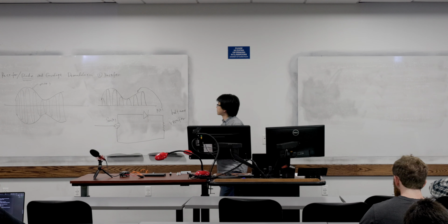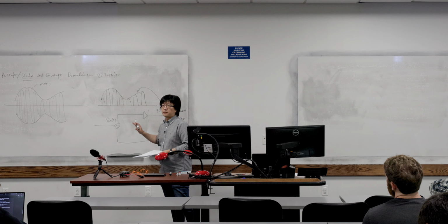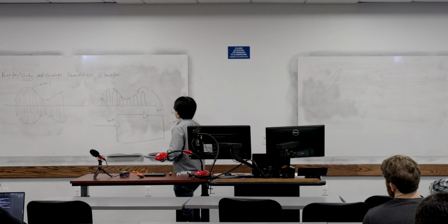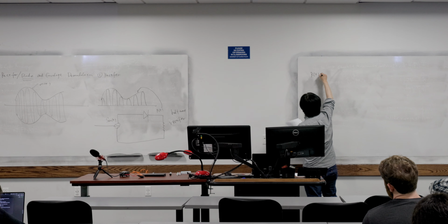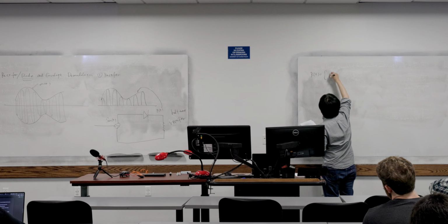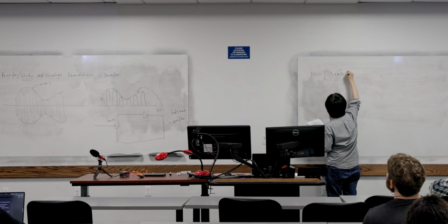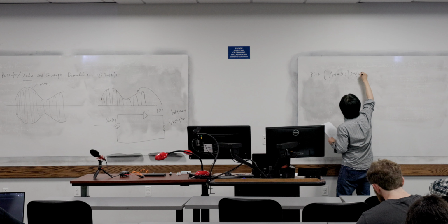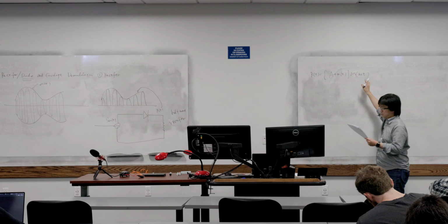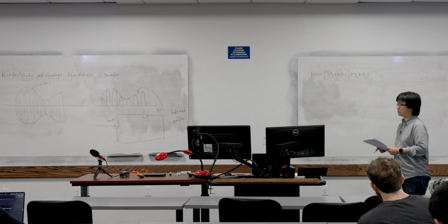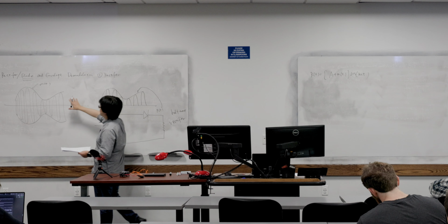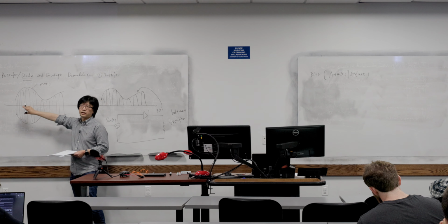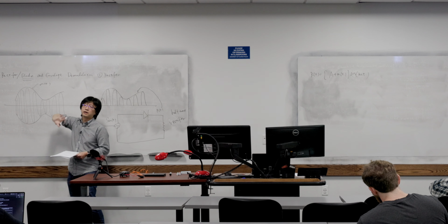Great. Now let's see how we can do that mathematically. This is what is happening. Equivalently, r(t) equals nothing but as follows. This is our AM signal. What we do here is that we multiply this signal by a square waveform, but only on the positive side.